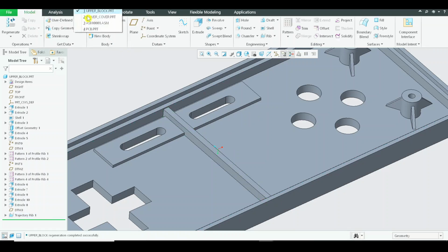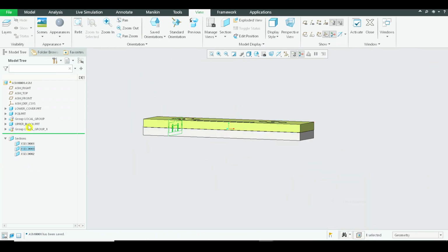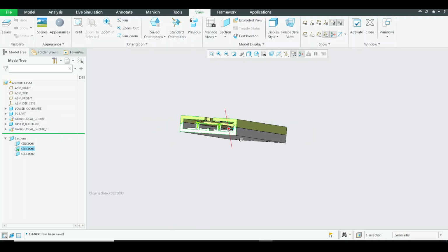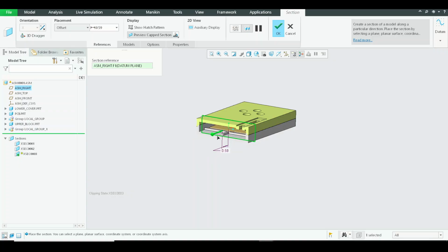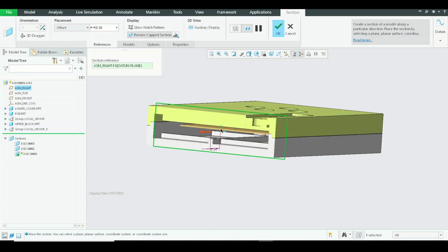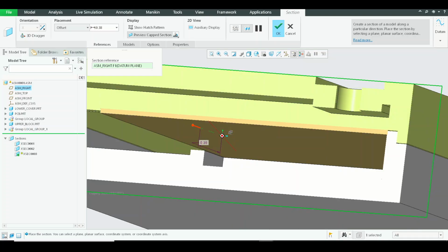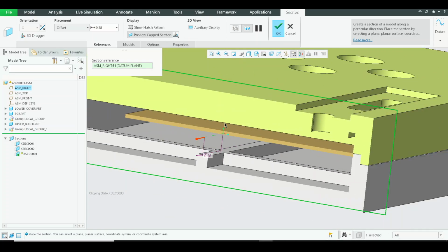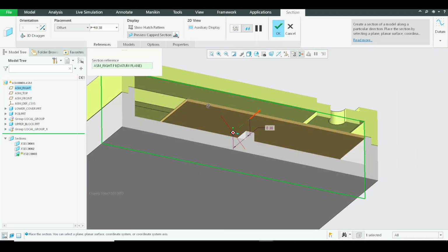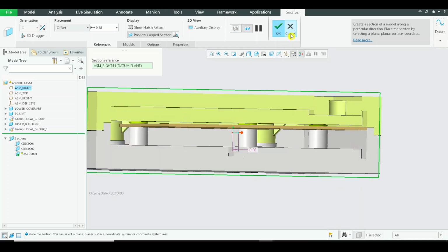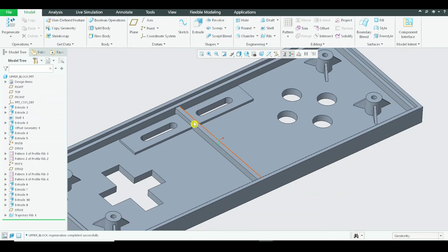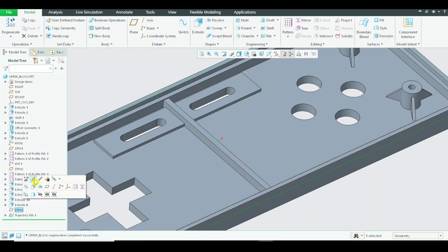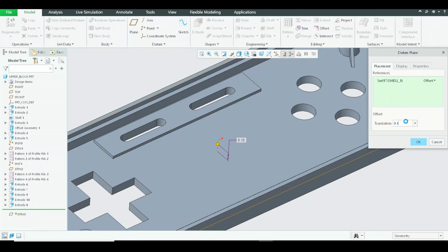Let us move to the assembly again and analyze a cross-sectional view. The placement of a rib shouldn't touch the parts of the PCB board, but this looks extremely close to the PCB board, and you'll have some electronic components which will obviously be placed in this region. So we need to reduce the height of the rib by moving the dimensions more inward.